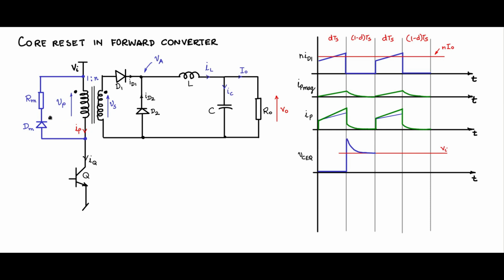And then IP current is decaying. As you see here, it is decaying exponentially, so the drop across Rm should also decay exponentially. Therefore, you see an exponential decay, and once the decay is complete, it will settle at Vi, because once this is off, it is only Vi that will come at this point. So this is how the voltage across the BJT will look, and then it will repeat again the next cycle and decay in this fashion.